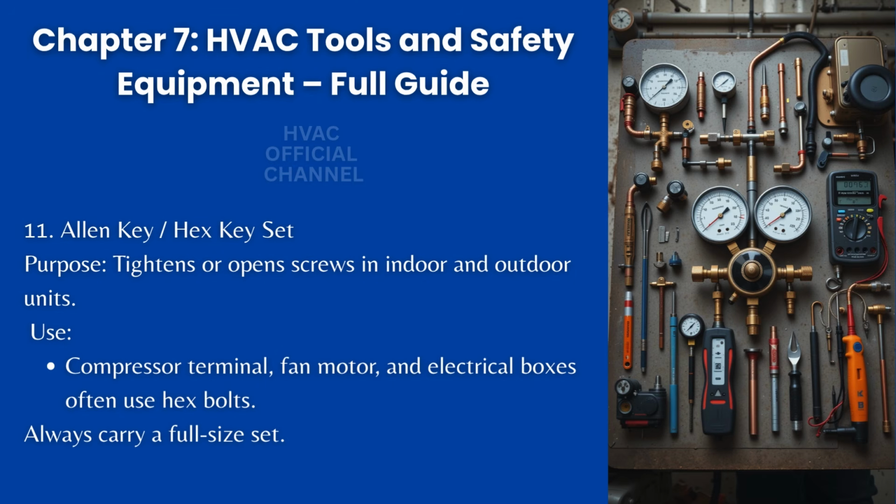11. Allen key, hex key set. Purpose: tightens or opens screws in indoor and outdoor units. Use: compressor terminal, fan motor, and electrical boxes often use hex bolts. Always carry a full-size set.